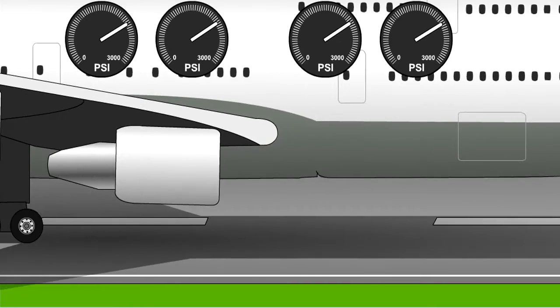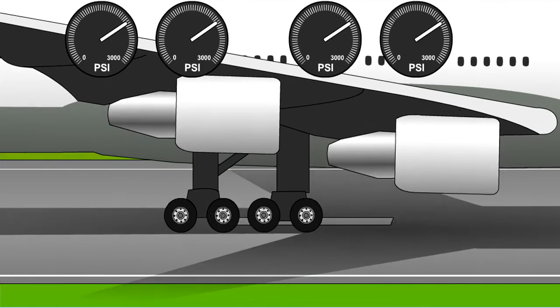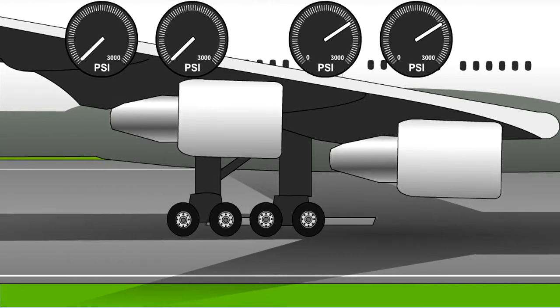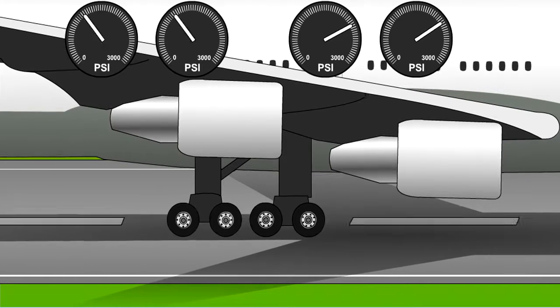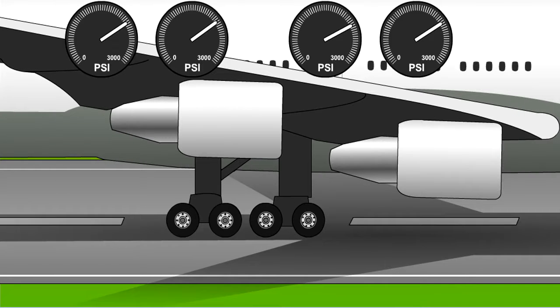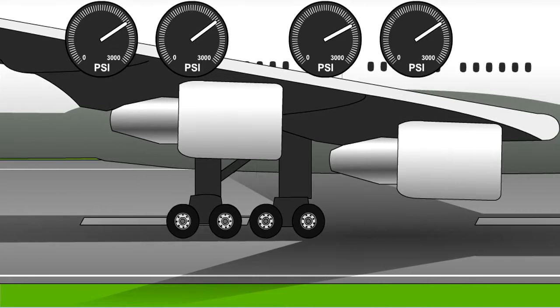If a wheel locks because of a wet patch or ice, for instance, the anti-skid controller will release the brake pressure to that wheel completely until the wheel spins up again. Then the pressure will be reapplied. This feature is usually disabled at low speed.